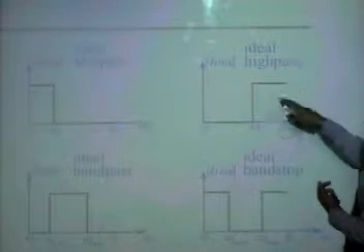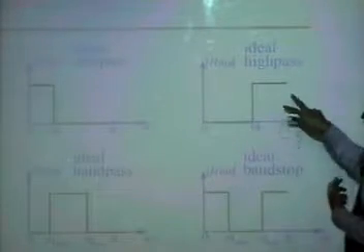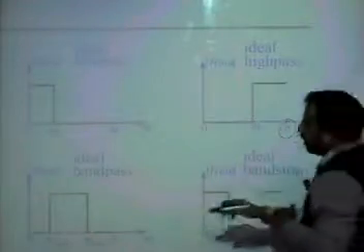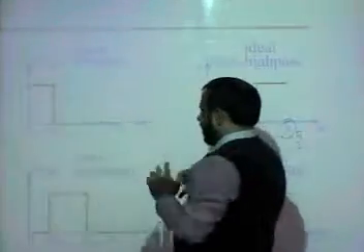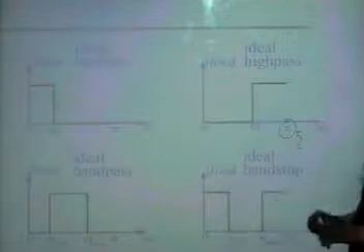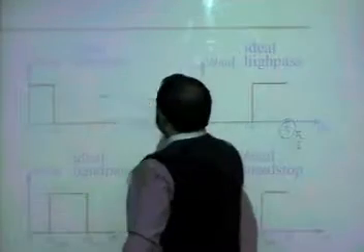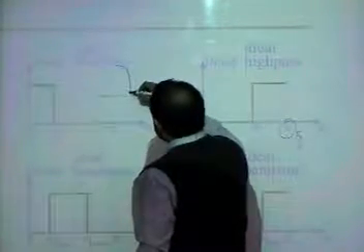So the important thing is, again, this is a high pass filter. It will pass this frequency content, it will stop the other. This is band pass, it will pass a band of frequencies, and this is band stop. It will stop this particular band. There may be a particular frequency which you want to stop. You say, I really want to only filter out this frequency.